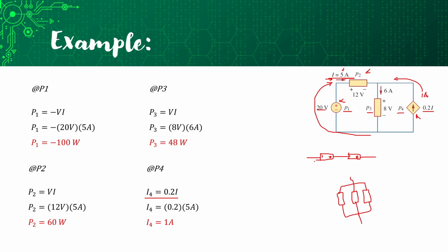The concept you need to know is that a circuit is in series if only one of their terminals is connected to each other. As you can see, for these two resistors, terminal 2 and terminal 1 are connected to each other, but the other terminals are not. Therefore, this connection is a series connection.